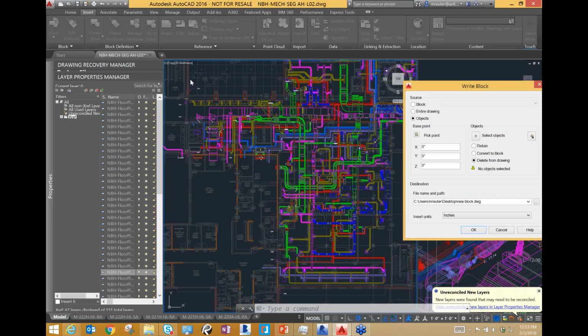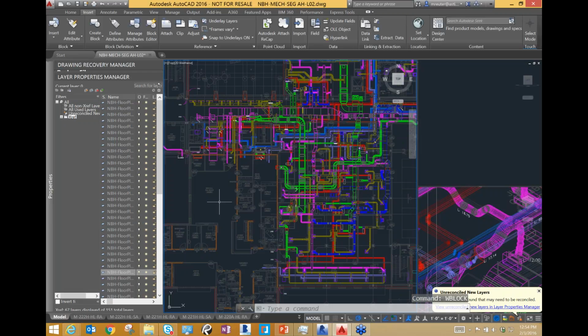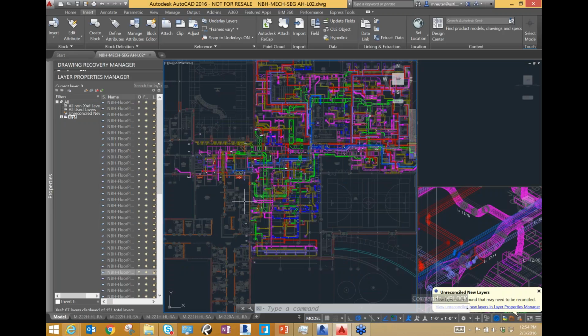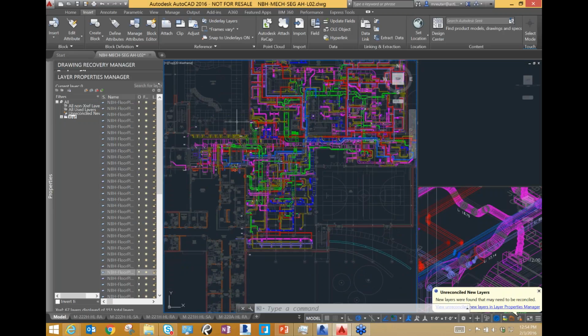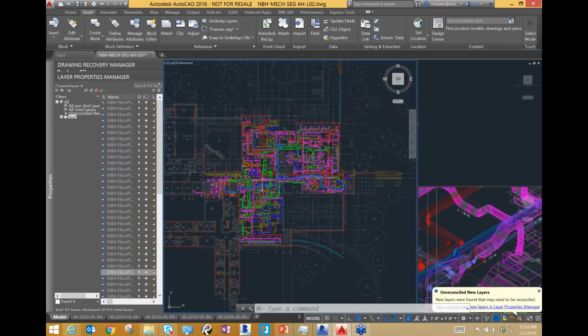But like the reason that we did that, I cut that, you would basically want to cut up your WBlock so that it made sense to you. So, for instance, the reason that I drew that shape was because these are actually two different segments that kind of come across right here, and so I wasn't particularly concerned with anything that is north of this column line or east of this column line right here. So I wasn't going to be clashing that stuff together.